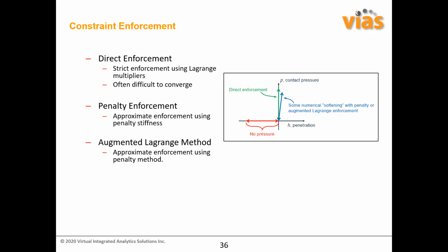So you can allow some numerical softening. What it means is that the surfaces can penetrate a little bit. This little bit really has to be in the context of your problem. Of course, you cannot allow a penetration of 1 meter between the bodies, or even 10 centimeters, maybe 0.1 inch, 0.01 inch, or speaking in millimeters, maybe a couple of millimeters. But if the scale of your problem is very small, if you are dealing with a micro-mechanical type of system, then all of these tolerances may have to be decreased accordingly. It depends upon the scale of the problem that you are talking about.